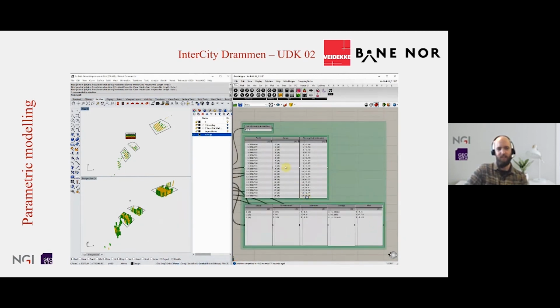some summary statistics. So we can see that in my 3 groups here, I have 477 columns, and I can, in this panel, list all the deviations for each column. I can also review some group summaries. So I have 3 groups, and I can see the column count. And all columns are minimum ½ meter too short, as set by my criterion. The average length is about ½ meter to 1 meter too short, and the shortest column is 4.5 meters too short in the first group.